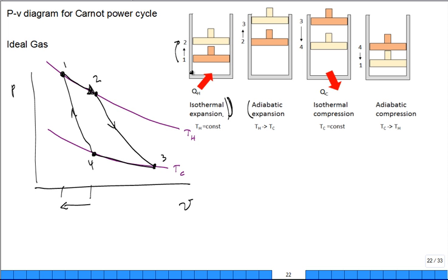And if you just heated it up at constant volume, the pressure would go up, right? So what's going to happen is you're heating it up to try to keep it at the same temperature. So don't let it conceptually be constant volume heating in your mind. Let it expand such that it's constant temperature. It's isothermal expansion, heating from 1 to 2. Now, 2 to 3 may be a little easier because you have no heat transfer and you're just rapidly expanding. The temperature and the pressure are going to drop. All right?